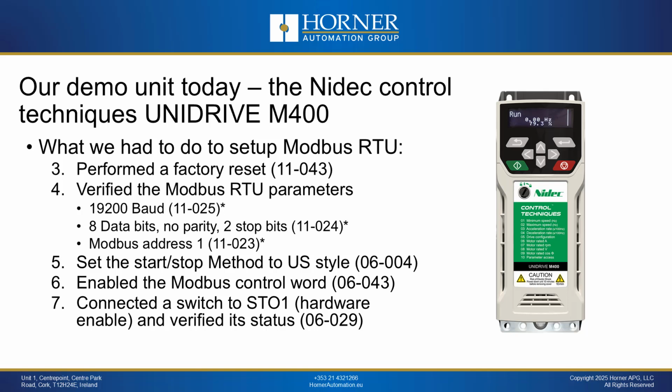Next, we set the start-stop method we wanted to use for the drive to the US style. The M400 has a Europe style and a US style. Start-stop method, we choose the US style in menu 6. We also enabled the Modbus control word in menu 6, parameter 43.